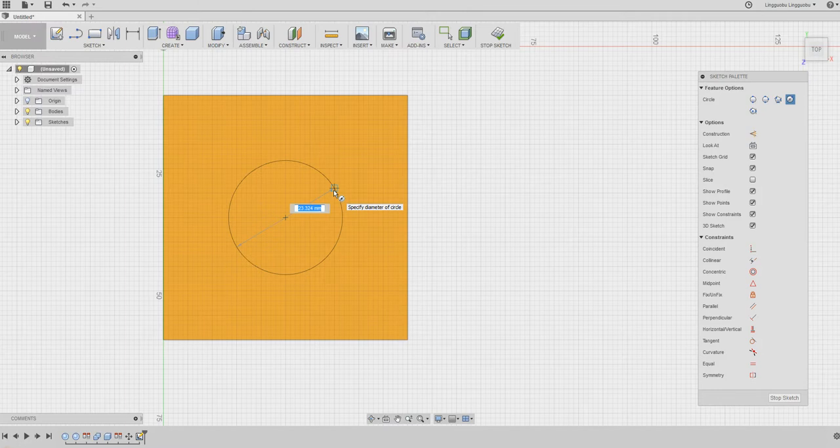And as I said, it should be the diameter of the big sphere divided by the square root of 2. It turns out Fusion 360 allows you to use SQRT for square root of 2, and that's pretty much the same across all programming languages.